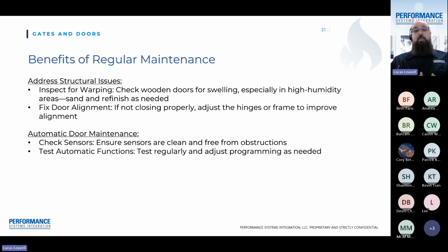As I mentioned, hinges, believe it or not, are the number one cause of a door being unable to be used. The hinge has just gotten loose and now it's scraping along one spot and hanging, or it could be stuck and jammed. Yes, you can have a door that gets so swollen it will stick in the door frame. But if you're dealing with security doors, a gate, or anything made of metal, swelling is much less of a concern and the hinge becomes a much higher concern. Not to say that hinges aren't a problem with wooden doors.